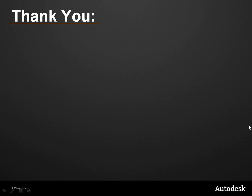It recognizes it, so it can take it in and view it based on, for example, bare earth. If it's already classified, you can toggle on bare earth and you'll see bare earth. You can say build a surface in Civil 3D from bare earth. So based on what's turned on from a point cloud, which can have many millions of points in Civil 3D, we could say turn on bare earth, build a surface, and in 2011 it'll automatically build the surface from bare earth.